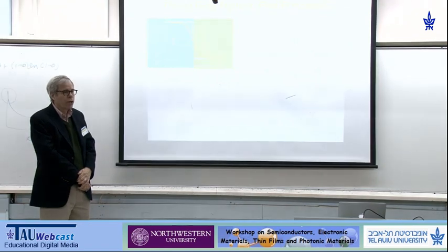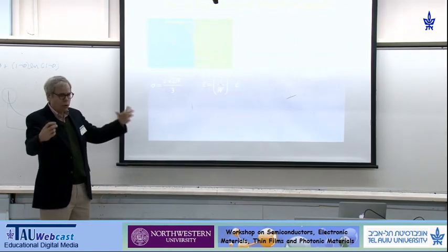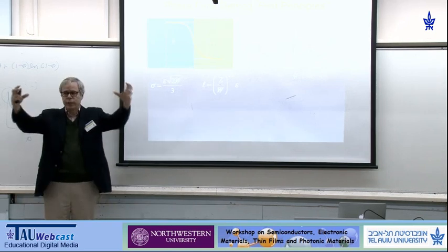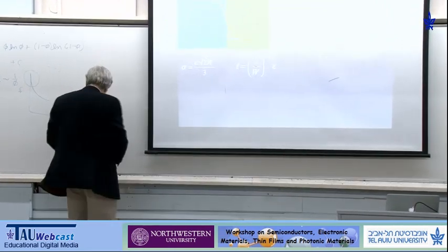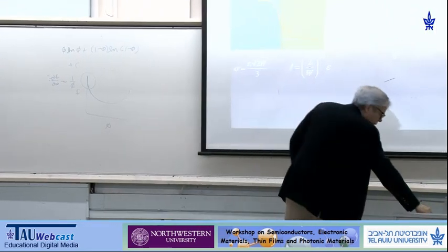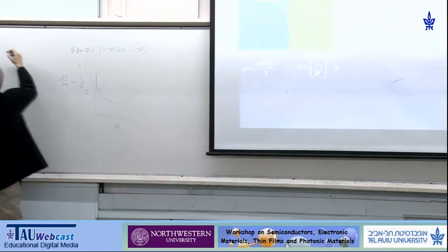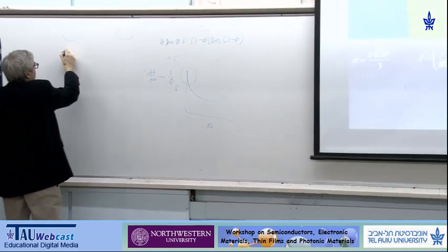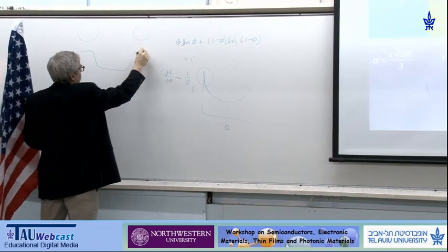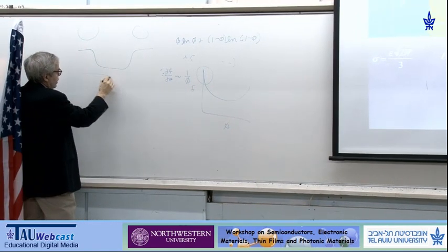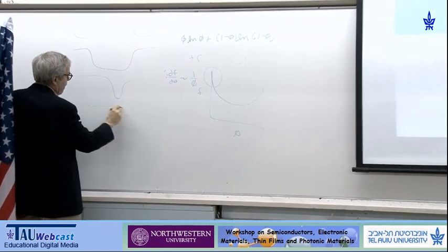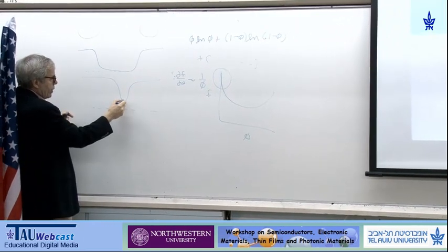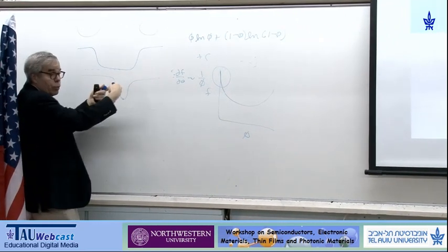One of the really interesting ideas is that during coalescence, you have two particles. For those of you who don't know what David's talking about, you take 2 particles, you bring them close together, and you think about what's happening. You have this diffuse interface over here, and this diffuse interface over here. One particle, another particle, each with a diffuse interface. You start bringing them close together, and they begin to come together, and this point here eventually disappears and the 2 particles coalesce.